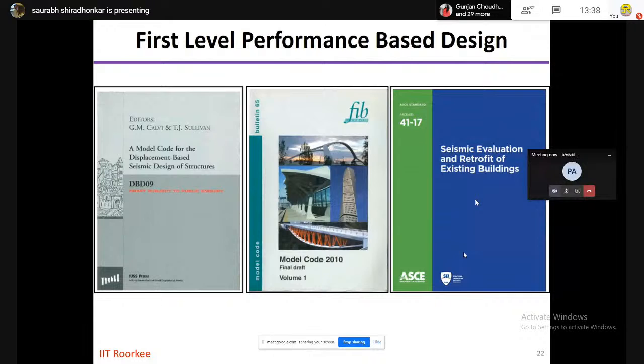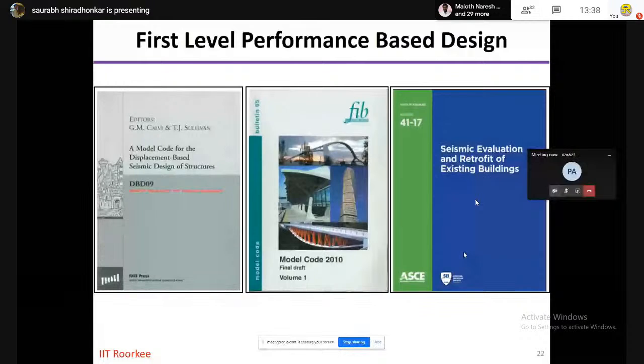So if you can understand that the force-based method is based on the extension of Newton's second law, where you can say that the forces which are coming onto the structure are proportionate to the inertial forces of the building and the earthquake acceleration. However, in these methods, you can idealize the earthquake ground motion as the displacement. It has been displacement that has been applied at various structural parts or at the various structural levels.